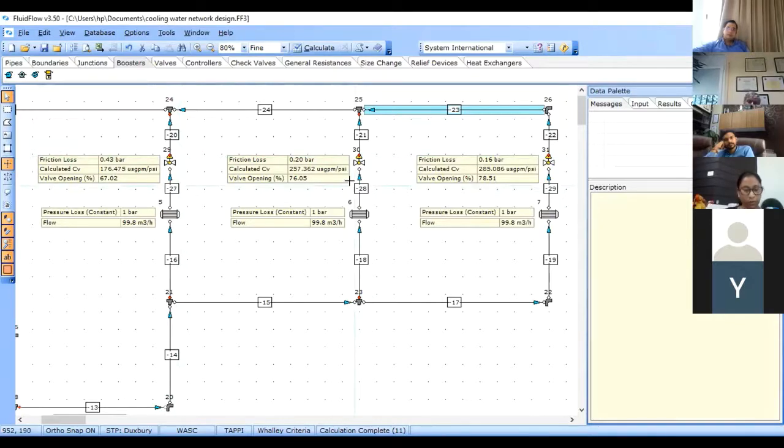All right. What is the advantage of using the control valve here, sir, when the orifice is much cheaper than a control valve? This also I had explained. If the process side flow is more or less the same in all the scenarios, then you can get away with a restriction orifice. Otherwise you have to use a flow control valve.